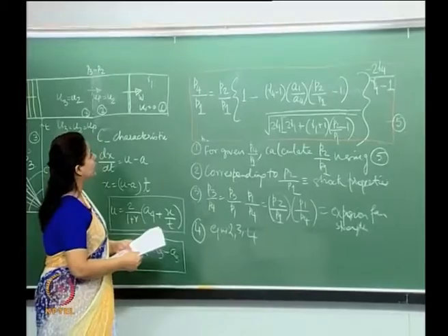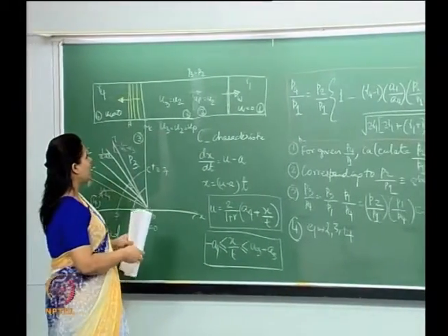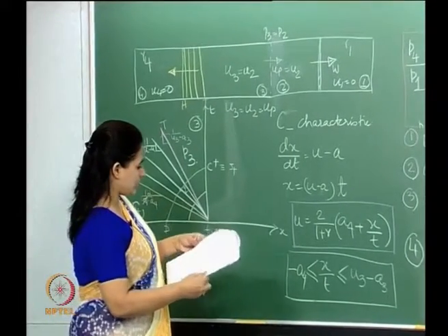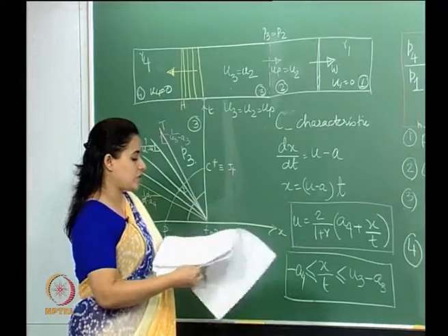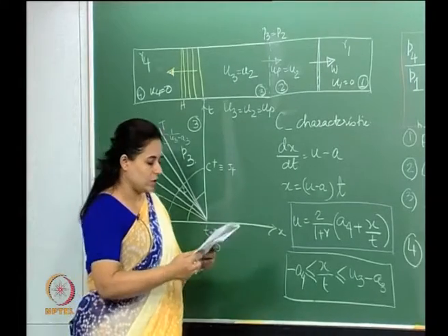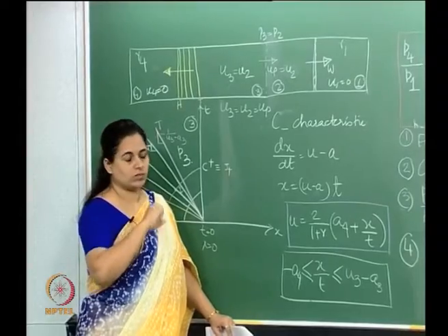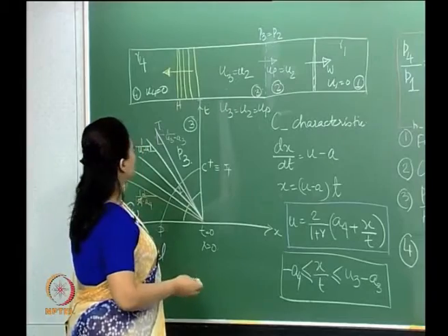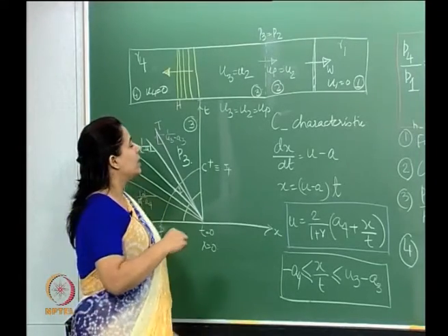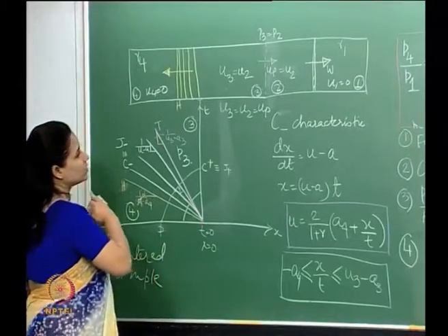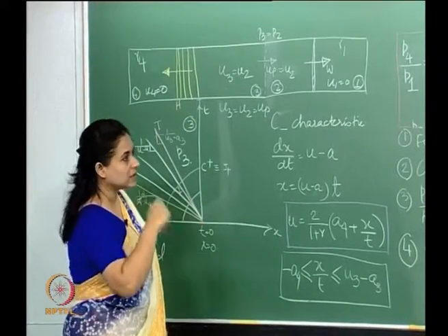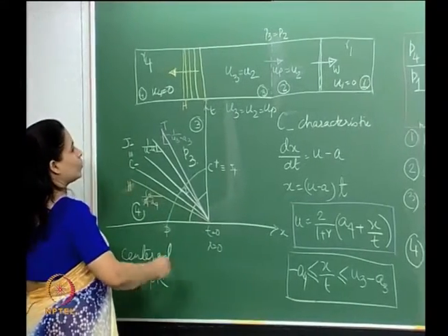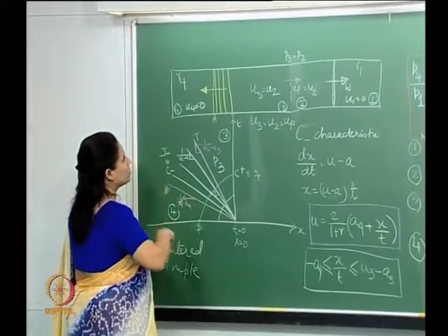Okay. So, that pretty much gives us a solution for the shock tube. Now let us go back to the picture that I had drawn right at the beginning, which you did not have any way of deciding whether it was correct or to agree with or not. So, let us revisit that one more time. Essentially, what I am going to try and do is plot the pressures, temperatures, densities and velocity, and see if what I had drawn right at the beginning is something that you agree with.